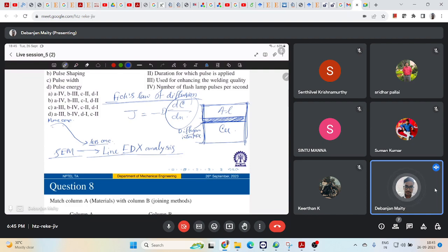At this diffusion interface, you will have both aluminum and copper at some specific composition and forming some specific phase, depending on your temperature and pressure, which you can also understand from the phase diagram. Now, why am I talking about this?